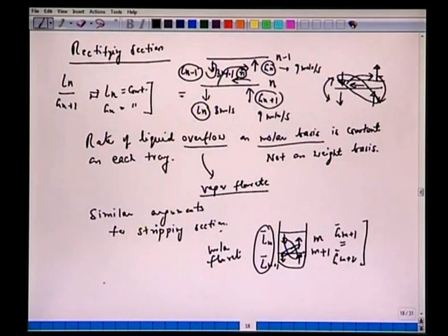All right, so we can also write here L bar. The bar here means the molar flow rates for the stripping section. Of course, you must note that L bar is not the same as L. Molar flow rates in the two sections are different. Why? Because we have the feed entry in between. We'll talk about this later in detail, but L without any bar represents the rectifying section, and L bar represents the molar flow rate for the stripping section.